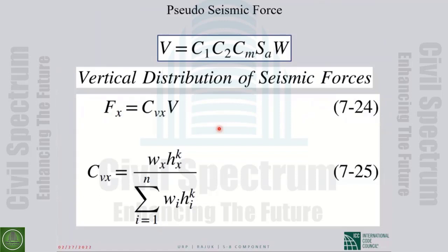If you do a pushover, for example, nonlinear static analysis, if the gravity load is there, you push, changes happen at a specific location. If the gravity load is not there and you push, the distribution of hinges is completely different. And then if you combine the result of the gravity load with this one, the results won't be similar to the other one. The superposition is not valid in nonlinear analysis. But for the linear analysis, very nice.